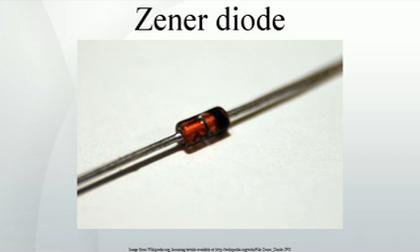The emitter-base Zener diodes can handle only smaller currents as the energy is dissipated in the base depletion region, which is very small. Higher amount of dissipated energy, higher current for longer time, or a short very high current spike, causes thermal damage to the junction and/or its contacts. Partial damage of the junction can shift its Zener voltage. Total destruction of the Zener junction by overheating it and causing migration of metallization across the junction. Spiking can be used intentionally as a Zener zap antifuse.